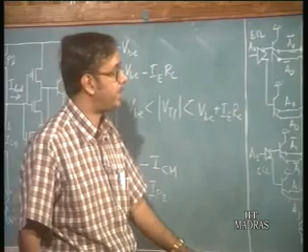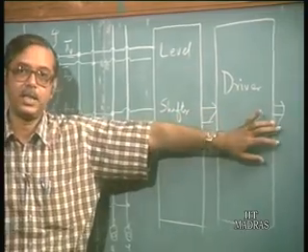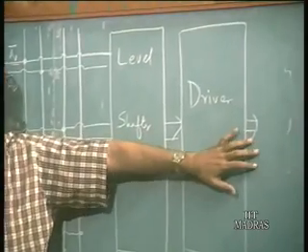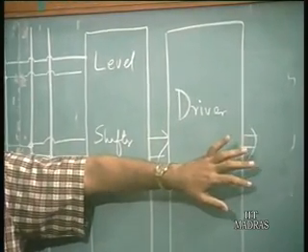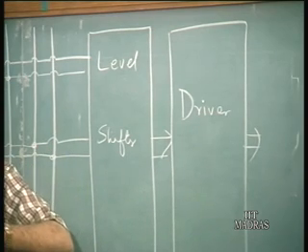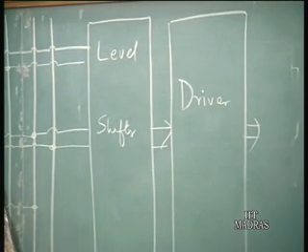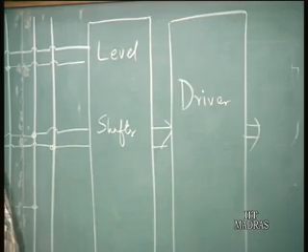The important point here is that although at the input you have ECL levels, at the output of the driver you have basically CMOS levels, except that the voltages are driven negative. So it is level shifted down. There is a level shift to negative values, but the voltage levels are still the same as in CMOS.